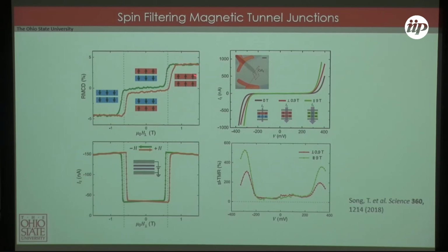You can look at the IV characteristics, and you see they're highly nonlinear. They're really flat, and then they turn on, because this is a pretty big tunneling structure. You have the van der Waals gap in between. You have the ferromagnets themselves, which insulate. So it's a pretty insulating structure. And then there's a turn on. Okay? And the point is, the purple curve is in no field, right? The anti-parallel state. There's a turn on that starts off later.